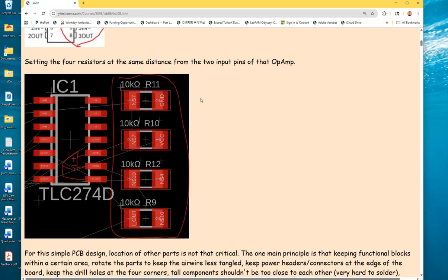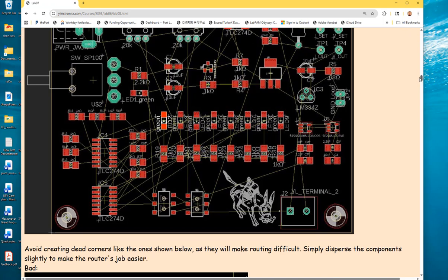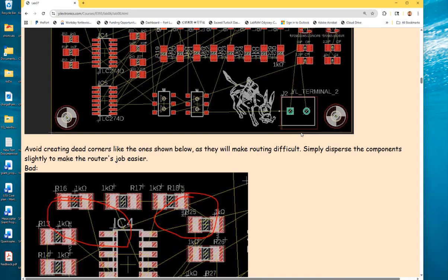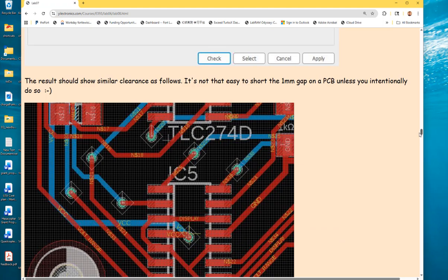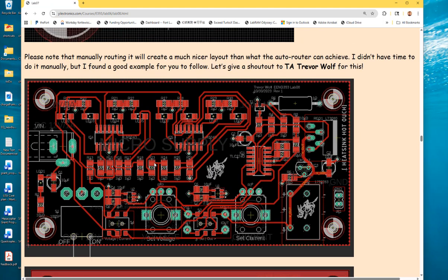And the third one is the layout. So for laying out the PCB, you want to manually draw the traces instead of using auto routing, because the auto router just creates a super ugly PCB. But you can see this example from one of the students at Mines. He spent 8 hours to manually lay out everything by hand. So this is a very good example of doing that.